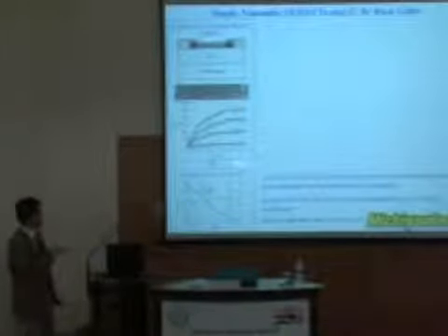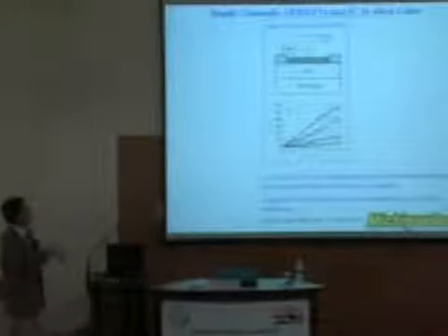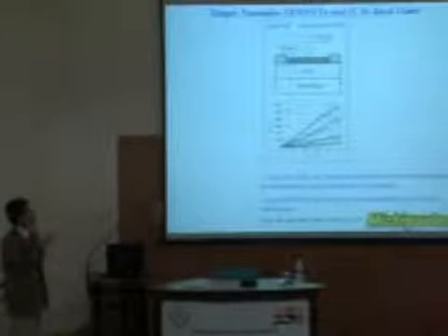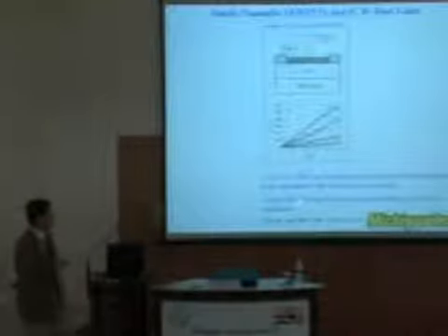And from here, this paper already defined how to form the so-called inverter, a logic circuit, based on the p-type nanotubes. Or alternatively, you can dope by evaporating some sodium vapor on the nanotubes. You can convert the p-type to n-type nanotubes. And in this case, if you combine both the p and n types together, you basically can form the complementary logic circuit as shown here.